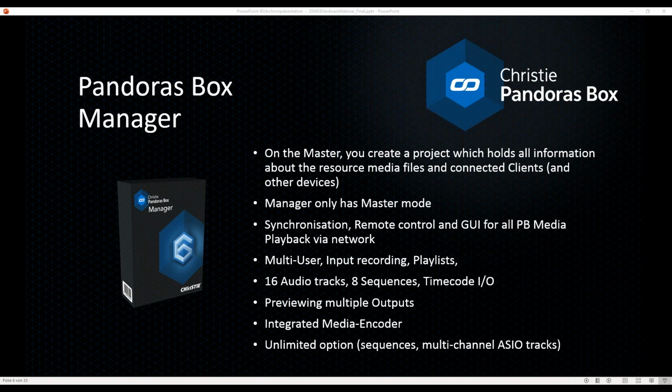You can set up, I think, up to 8 different previews in a thing, but you must be aware of performance issues. So for programming the show, this is very nice to see all the 8 outputs, but don't do it for a show, like most of the people who work with Pandoras Box know before. It will kill a lot of performance.